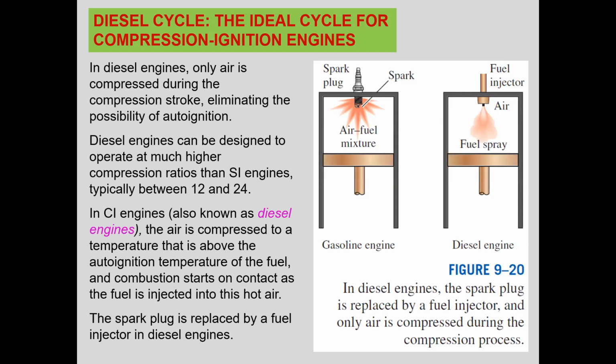Okay, so the self-ignition starts when the fuel is injected into the hot air at the end of the compression stroke. And for this to happen, compression ratio should be high, and usually it is between 12 and 24.